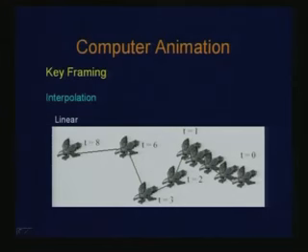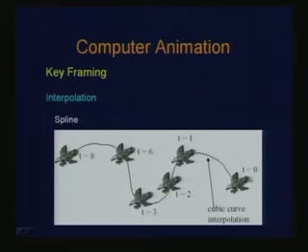So, wherever a joint is coming, I will see a discontinuity in the path and that would give me some jerky motion, right. This, as I said, could be corrected if I had used a spline curve, right. If I had, let us say, used cubic curve interpolation, then I would see a smooth transition over this path, right. So, the path is continuous.